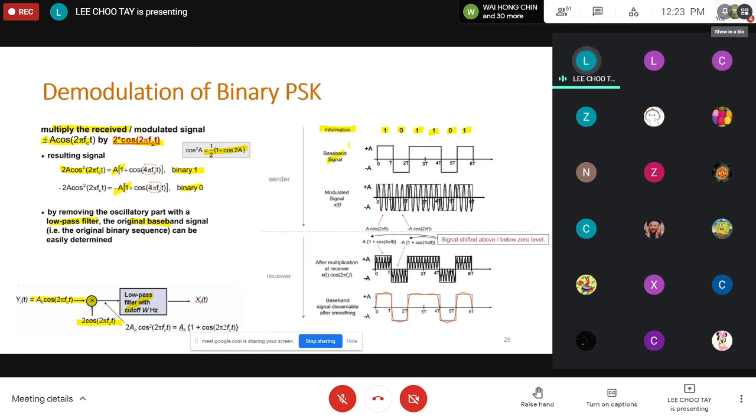For the baseband signal, for a binary 1 we use a positive pulse. Again, this is a non-return to zero polar line code. So 1, we use a positive pulse. 0, we use a negative rectangular pulse. So 2 ones, then continuous, then 0, then this is 1, this is 0, and then back to 1 again.